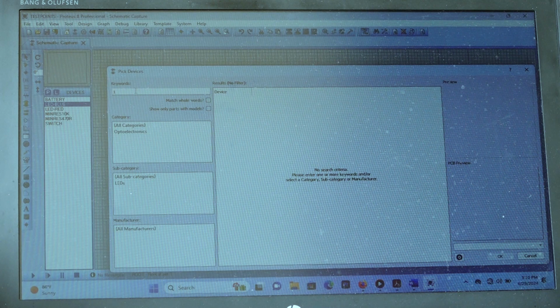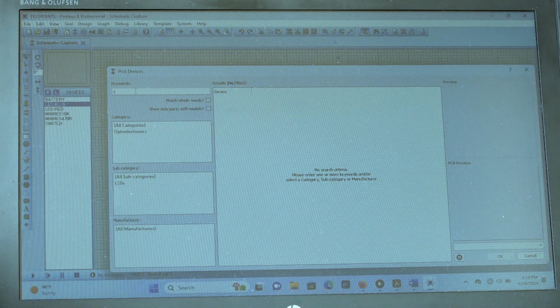I taught you, for all the resistors with a decimal point, we used to write the whole number, then the letter, which is the unit, representing the decimal point, and then the next number after the letter. So there we have 1.1 mega ohm.